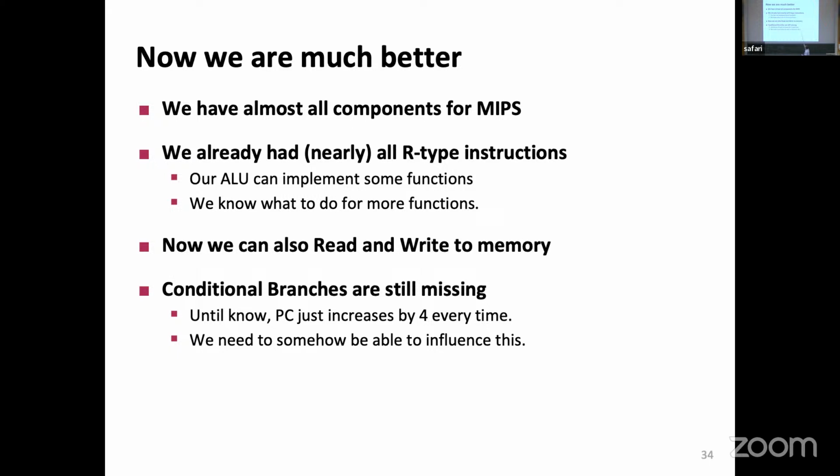And what we don't have is anything that allows us to manipulate this program counter. Our program always picks the next instruction, next instruction, next instruction. In computer terms, it's a completely unrolled program. Every instruction follows another, and at some point, I'm going to run out of instructions, and hopefully, Y2K problems, whatever, the world will end, kind of thing. So we need to have some instructions because this doesn't make sense. I need to be able to make loops. I need to have flow control. And for these things, I need to have some branches.